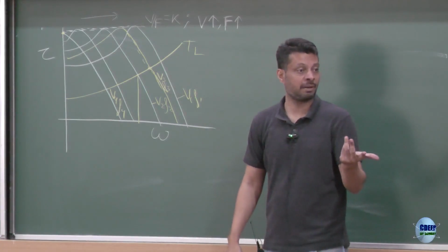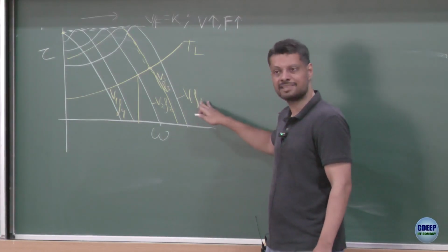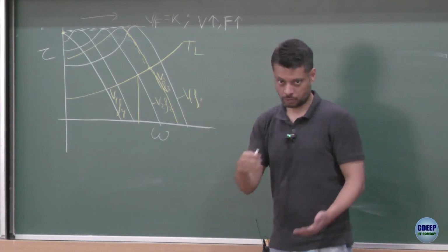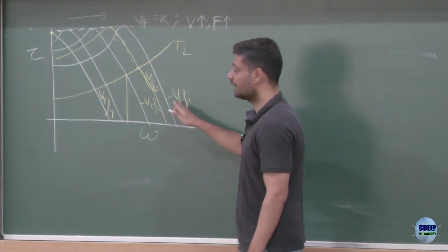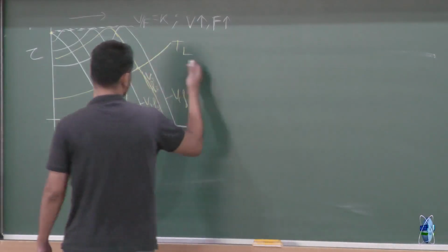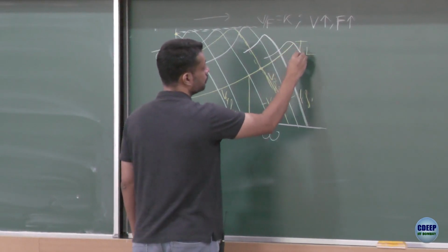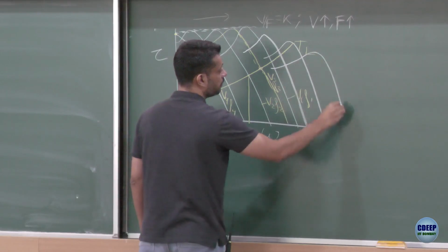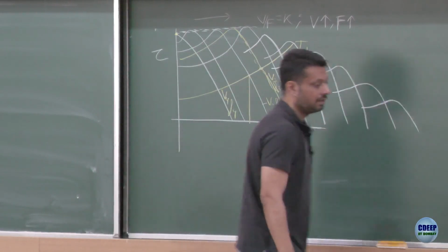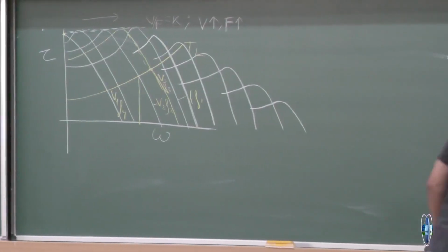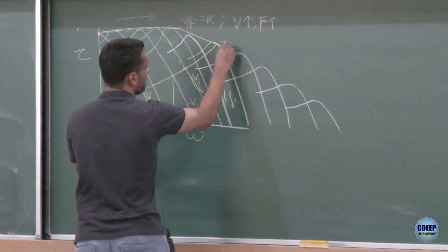DC motor we were able to operate by doing field weakening. Here what you do is after this you cannot increase the voltage, but you can still increase the frequency, right? You can go from 50 to 55, 55 to 60, 60 to 65, but the voltage is now limited to V1, and therefore the new set of characteristics after this looks something like this. So your peak torque does reduce, but you can go further ahead in the speed, right? And if you see the envelope of this new thing, the overall envelope looks like this.